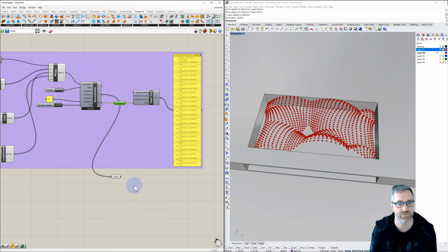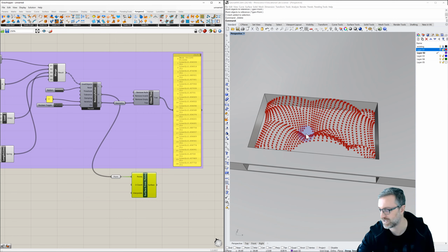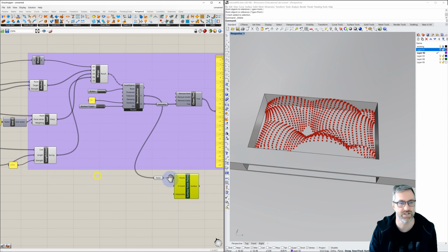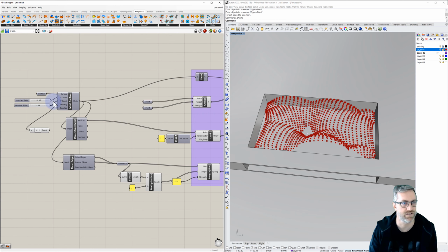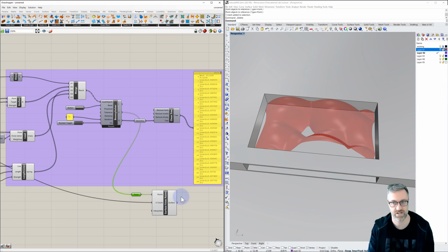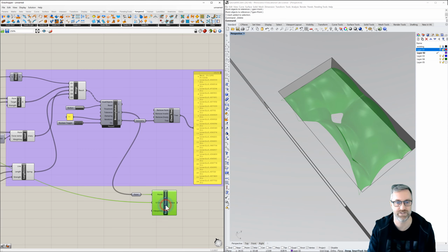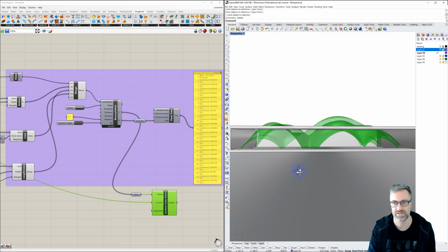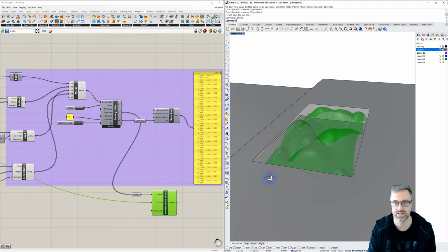What I'm going to do is there's a really nice command called surface from points. So we can create a, not surface points, but surface from points. We can create a NURBS surface using the points from the mesh. And so what we need in terms of U count is, let's pull, remember the difference between the count and the actual things. So the U count, we can plug into our expression. It's going to be +1. So let's just then scroll all the way over to the right and plug this in for our U count. So now we have a nice NURBS surface from our mesh. We can turn our points off. And now maybe this will allow us to zoom selected better. It's a little better. So now we have a nice NURBS surface from our mesh.